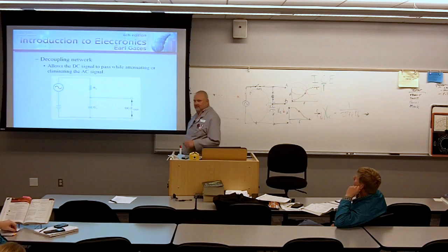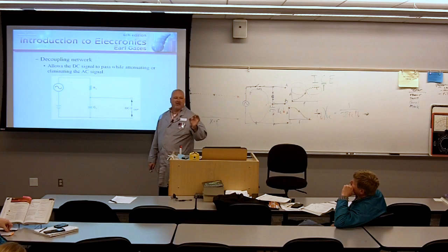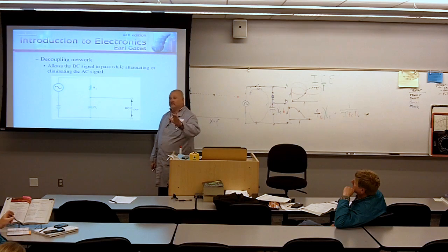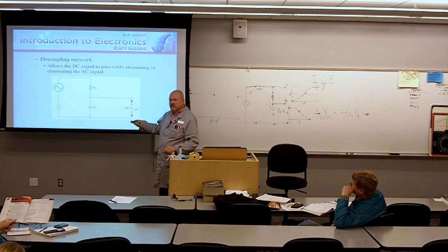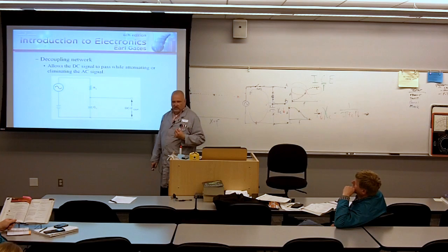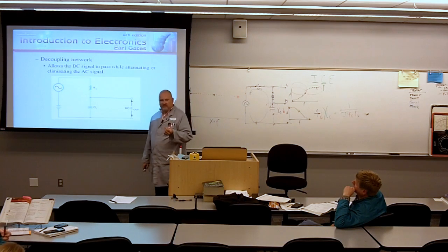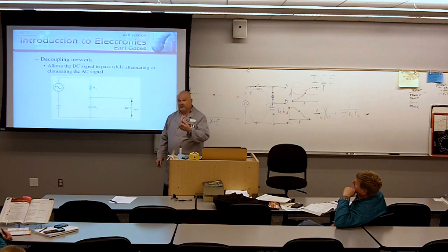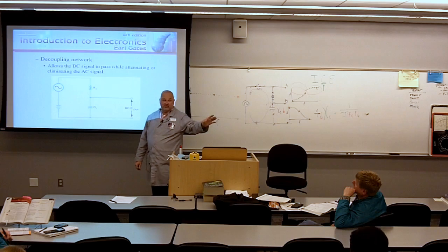What is this? This is a good one. What's the first thing I want you to pay attention to? Your sources. This is an AC-DC series RC circuit. Yep, absolutely, because typically DC is used to turn on semiconductor devices inside circuits, and AC represents the signal, the intelligence of what you're trying to amplify. So in most pieces of equipment, you're going to have AC and DC together. Sometimes you want to pull that DC off and let the AC just go on its way.